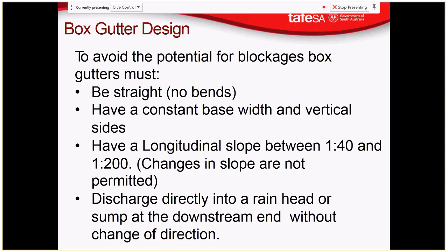Another thing we cannot do is do a box gutter like that. So that's what's called a V gutter. The issue with a V gutter is it's all in this little bit here. When you get steel, it's coated with zinc aluminum or galv or colour bond over zinc aluminum, whatever. When you bend it, you compromise the surface of that zinc aluminum or the galvanizing to a very small, sometimes very little compromising, but you compromise it.